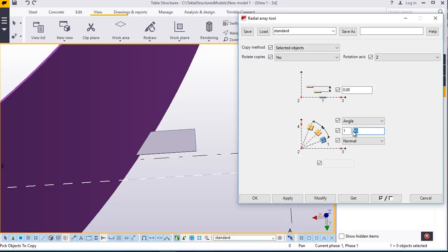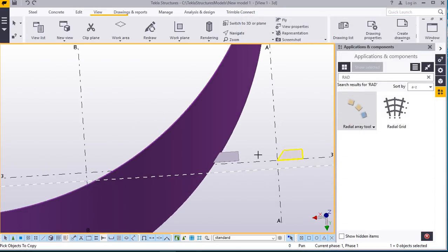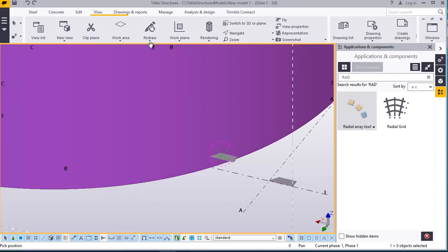Now we'll use an angle here of 2. Then we need 73 threads. Step of the threads, the spacing of the threads will be 200 millimeter right there. 200 millimeter. Go ahead and modify, apply and accept. We've made our changes or our settings for our staircase. I'll rotate this by going to view, navigate and rotate with mouse.